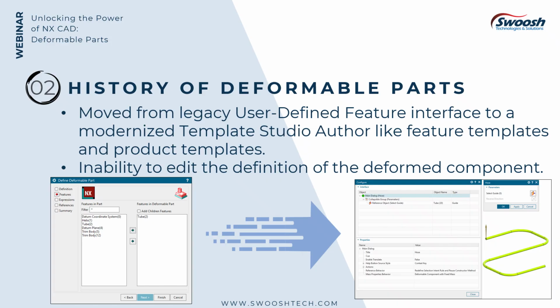Historically in NX, deformable parts were created and defined using the user-defined feature interface. This interface did not allow the editing of the deformed components. The capability was refreshed in NX 2406 with the authoring of deformable components now using the Template Studio author environment, just like feature templates and product templates.